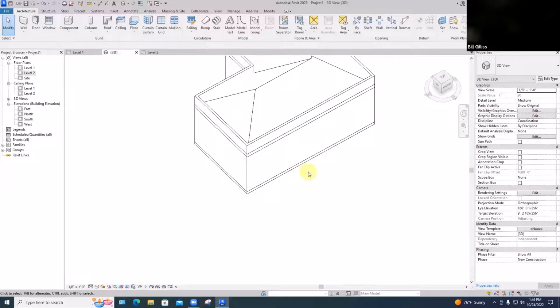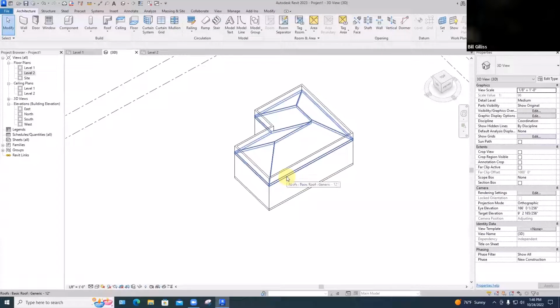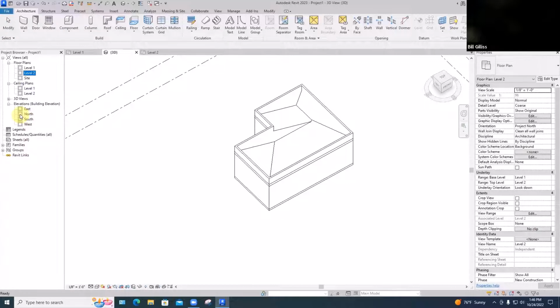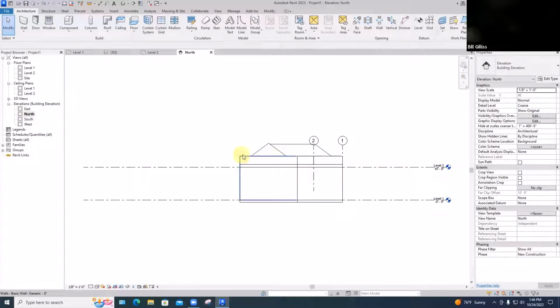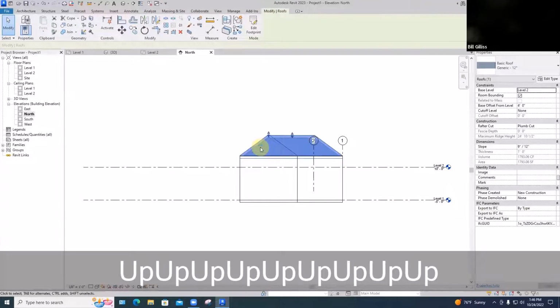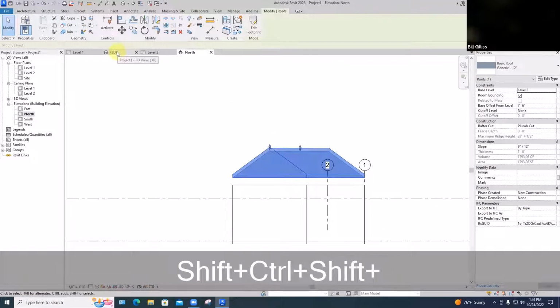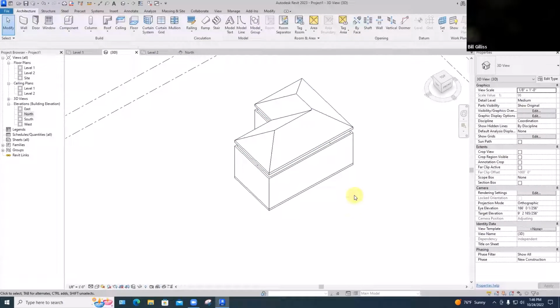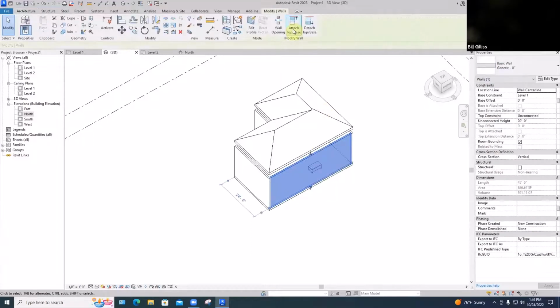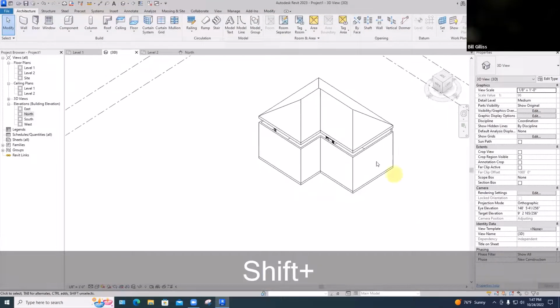Get back to 3D, and my roof is a little too far down, so I'll get into an elevation view, and pick it up. When I say that Revit understands buildings, it means it understands how they're put together and how the parts interact, and it knows that walls very often come up to a roof. So I'm going to pick this wall right here, say attach it to the roof, and then it'll extend it up there, and go around and do that for all of them.